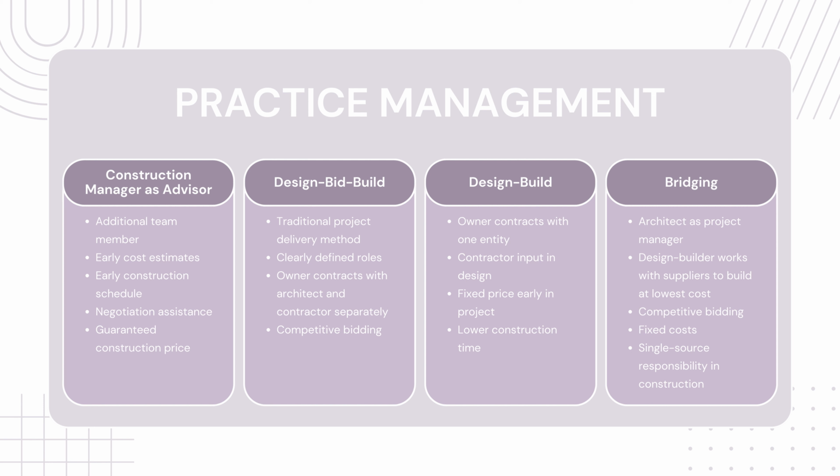Now keep in mind, design bid build is the traditional project delivery method. If you get a question on the exam and they don't state which delivery method it is, then it's safe to assume that it's design bid build. In design build, the owner contracts with one entity who does both the design and construction. The contractor is able to provide early input in the design, and the owner receives a fixed price early in the project. Construction time is typically lower than other delivery methods.